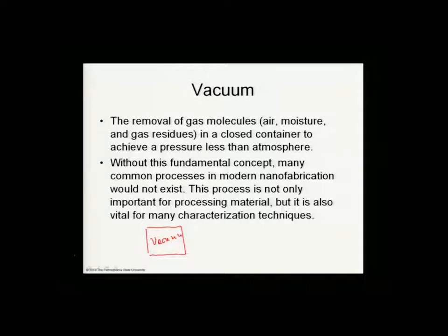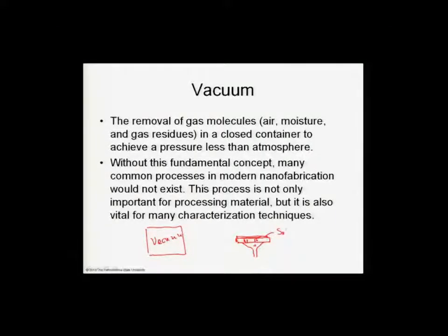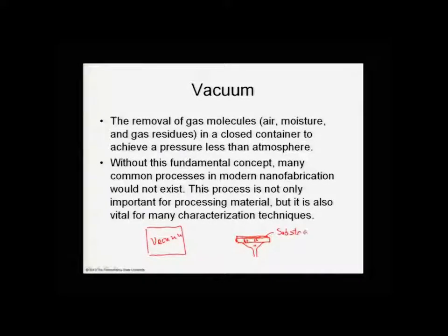There's another use of vacuum systems that I just want to mention, and that deals with taking a block and putting holes in it, and then having that off to a vacuum pump, and then putting your substrate, and then establishing a vacuum under here to hold the substrate down. This is a simple use of vacuum as a substrate holder. So we're just going to accept this. This is an everyday use of vacuum as a substrate holder.